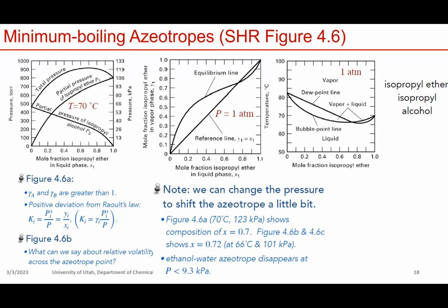So now, when we deal with an azeotropic system, as we just discussed, it's kind of hard for us to separate them, because if you start with a composition in this region, the best you can get is this point and that point. So you might be able to get pure phase A, but you won't be able to get pure phase B, right? You will get an azeotrope. That just makes the separation process hard.